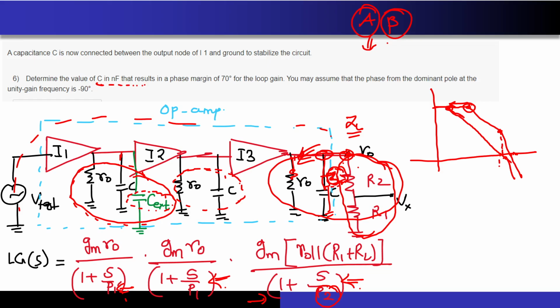Normally, you never find the phase margin for the closed loop system, because the whole point of calculating the phase margin was to not put the system in the closed loop feedback, because analyzing the transfer functions of closed loop systems becomes tougher and tougher as the order of the system increases, right? So we do the loop gain analysis first, then from there we calculate the transfer function without putting it in the feedback, then we do the phase margin analysis, and from the phase margin of the loop gain we estimate whether the system will be stable or not if I put it in the closed loop now. So that's why we have not taken G upon 1 plus G, because it does not make sense to calculate the phase margin of G upon 1 plus G.